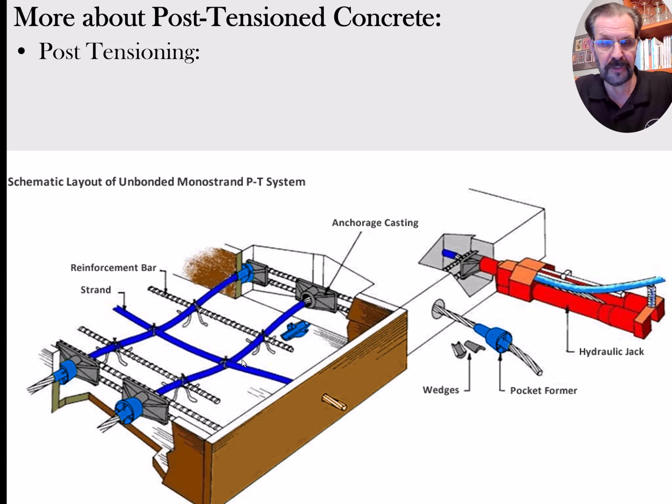Whereas for the post-tension cables that are in the thickened slab, the perimeter footings and various other grade beams, we would often have it droop down into the footing and back up where it can. So we get a similar process, but some of it will be in the center of the slab, equally compressing both directions, and so then there won't be a crown there. But anyways, I've got some pictures later on here I can show you on this.